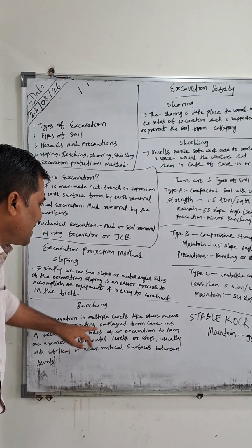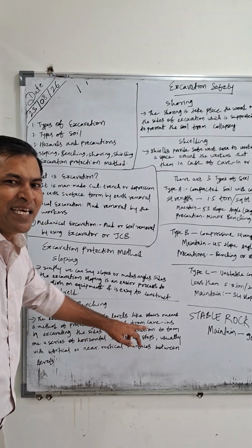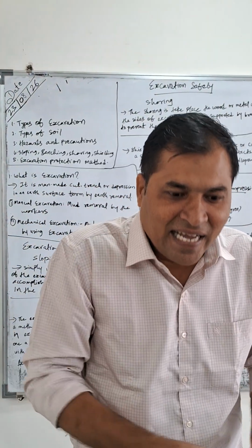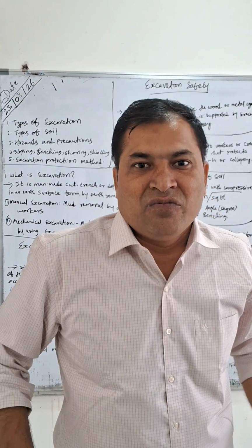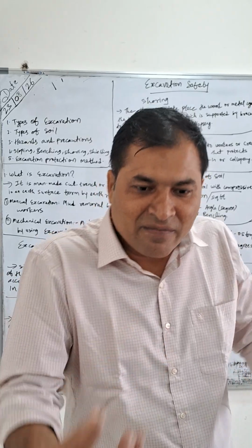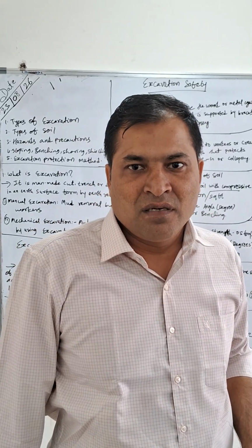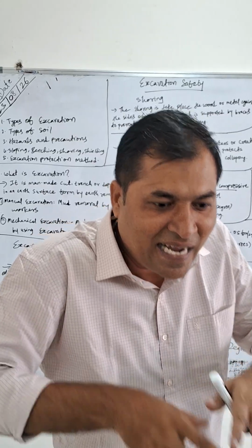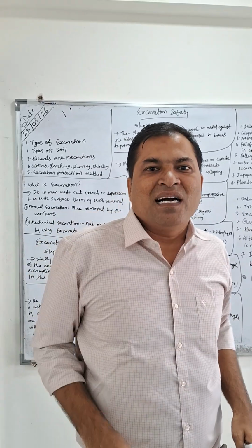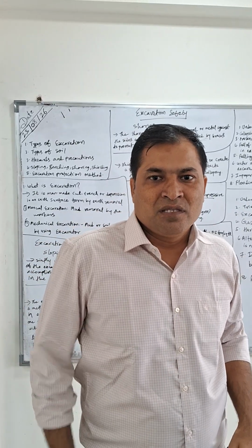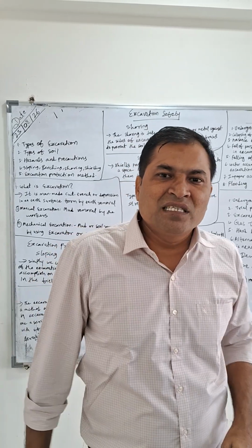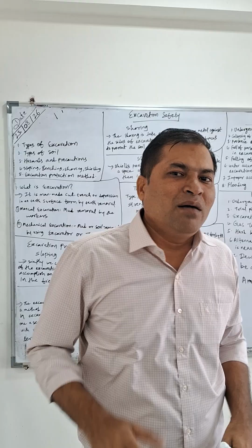It is a method of protecting employees from cave-ins. Cave-ins means what? The mud. If you are excavating, and suddenly the whole mud goes down, and at the same time water also comes onto the surface. If you are working there, water will accumulate on the surface area and the whole mud goes down. Again there is the problem. The workers were trapped inside. These are the major emergencies, so be careful about that as well.